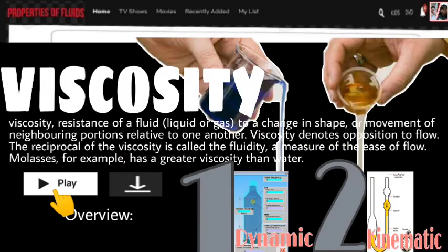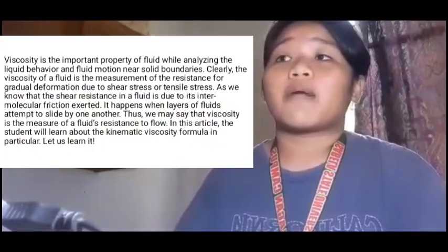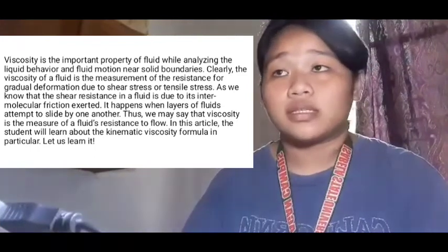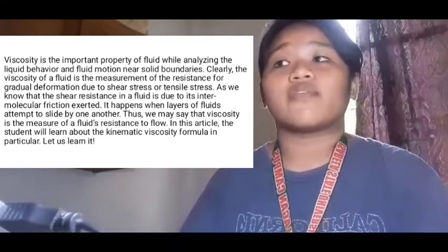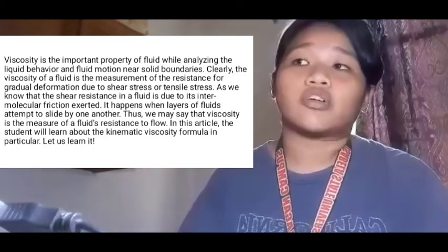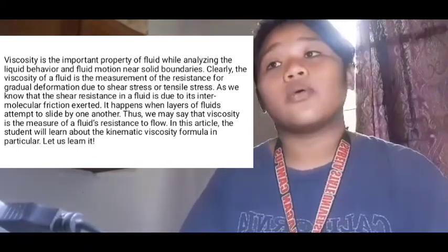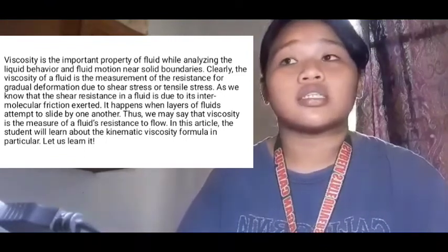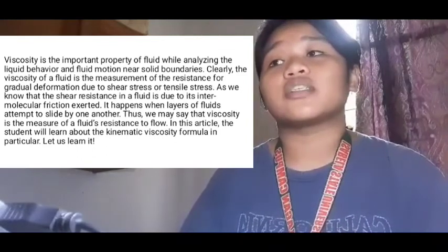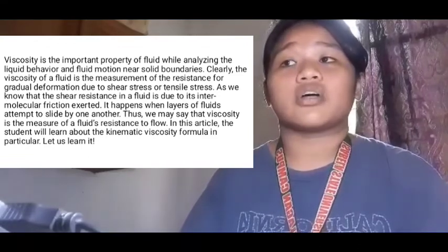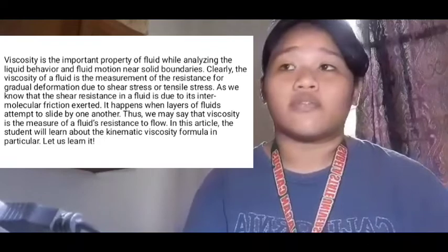Okay, let's talk about viscosity. Viscosity is the important property of fluid while analyzing the liquid behavior and fluid motion near solid boundaries. Clearly, the viscosity of a fluid is the measurement of the resistance for gradual deformation due to shear stress or tensile stress. As we know, the shear stress resistance in a fluid is due to its intermolecular friction exerted. It happens when layers of fluid attempt to slide by one another. Thus, we may say that viscosity is the measure of fluid's resistance to flow.